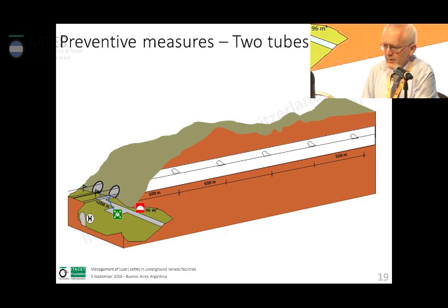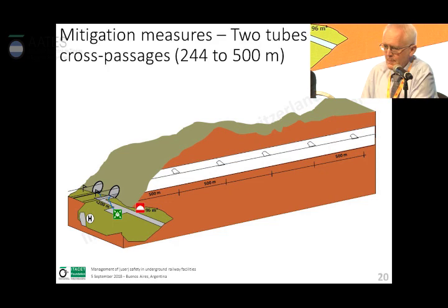Then a last example of a preventive measure is the choice of the tunnel system. So do we have a twin bore tunnel system or single bore twin track system. Of course, choosing already two tubes leads to avoiding certain incidents, for example, derailment, or avoids collision. So by this, you can already prevent fire as well by already splitting up the different traffic directions.